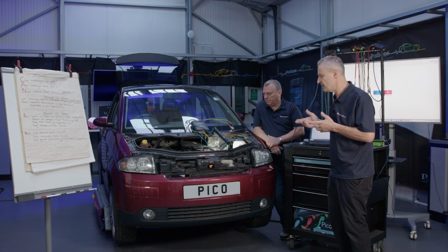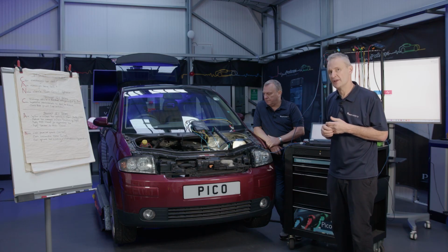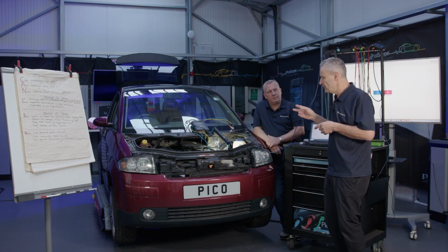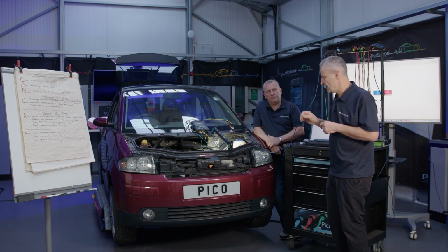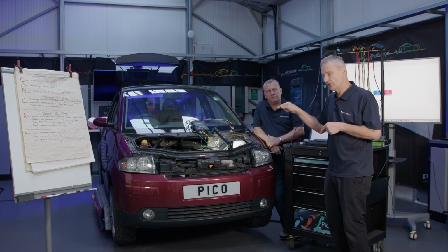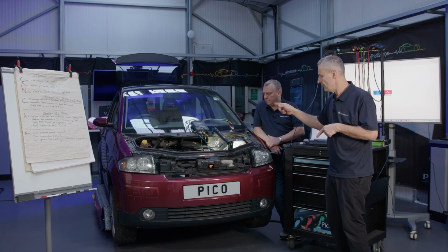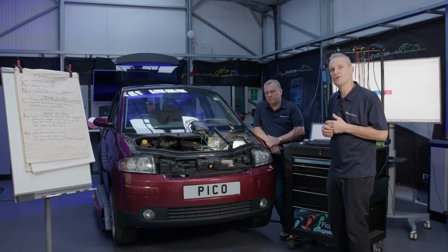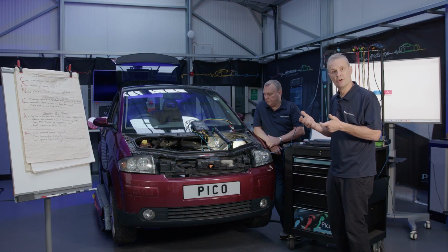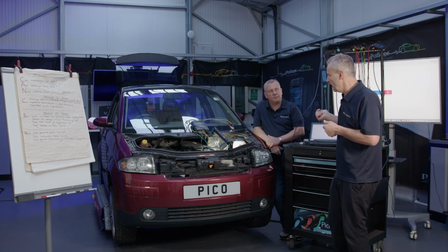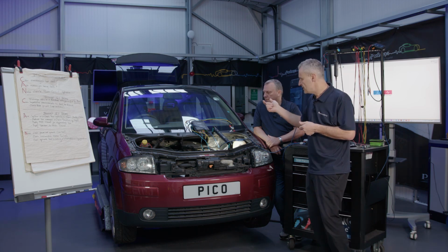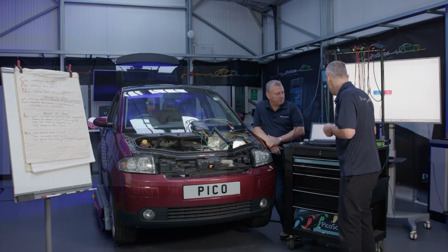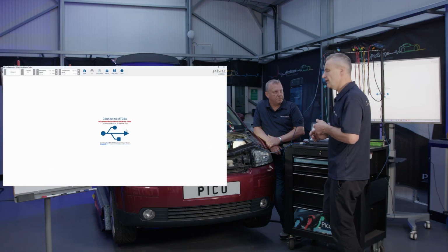So what's going to happen here is what we call a 4-wire measurement using the Kelvin method. We're actually going to measure with high accuracy by passing a current through the ground cable at the ABS ECU, reference to ground, actually see what the true value is, and then whilst we're in that position start moving the wiring harness and see what happens there. So USB connection to the milliohm meter. We're going to switch it to milliohm meter mode rather than using the motor tester.